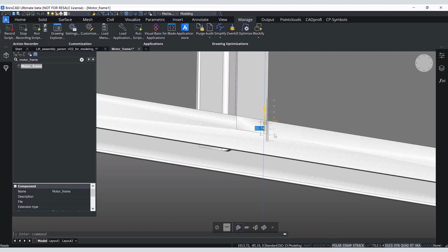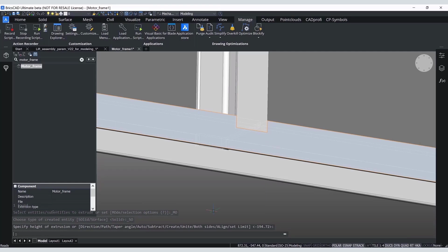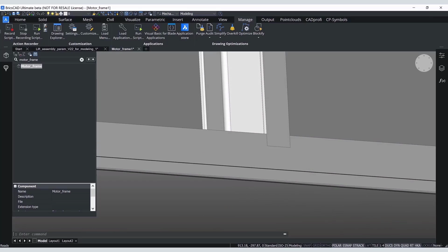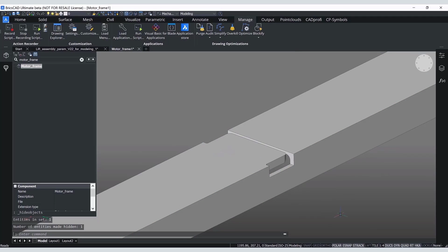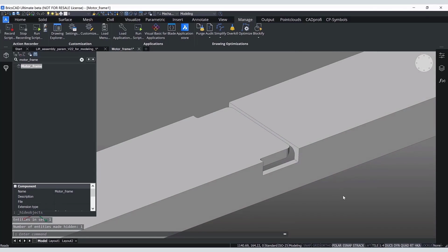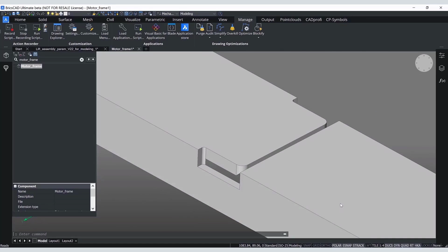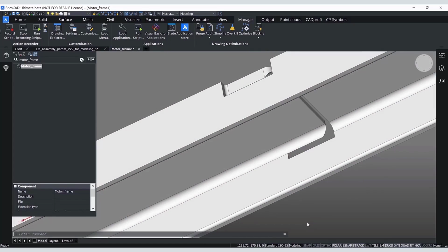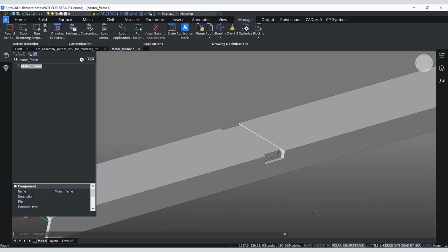Let's select this face to show how it will work. You can see that extruded solid united with initial one, so extruding looks like elongation. And here this new solid subtracts itself from intersected solid. Due to difference in working approaches in freeform modeling, BIM and mechanical, values of these settings are different for different workspaces.